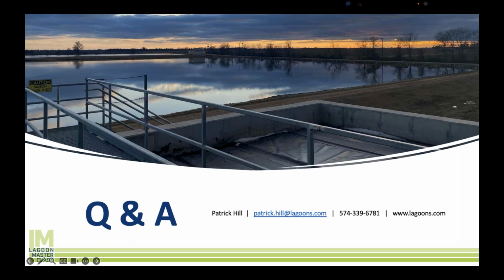Is there a recommended method of keeping duckweed out of a discharge? And have you heard of any states passing laws saying that discharging duckweed is equal to discharging the ammonia and phosphorus it takes up? No, I don't think there's any law there. I think the way to not discharge duckweed is to pull your effluent from the lagoon underneath the surface, like 2 feet below the surface.